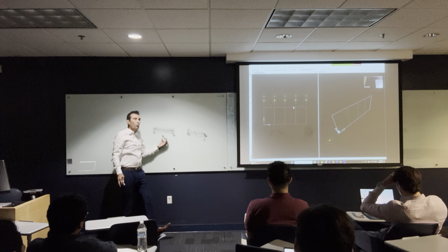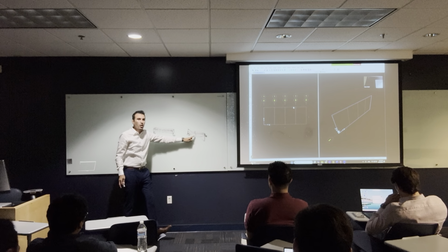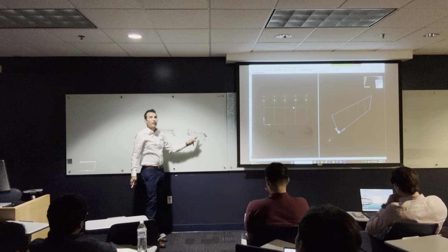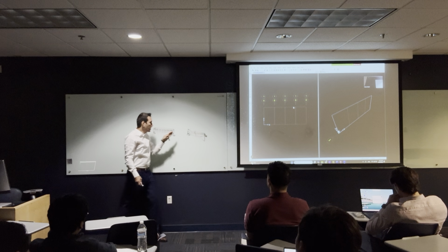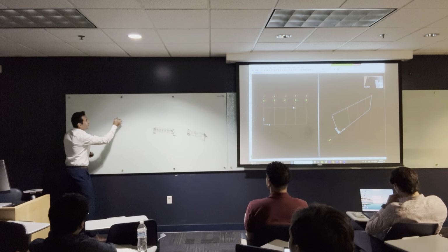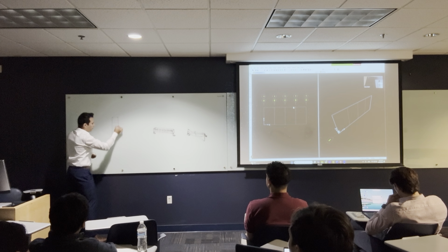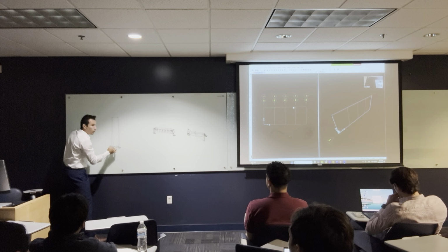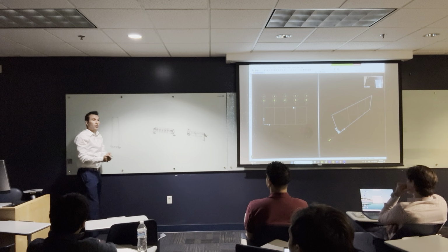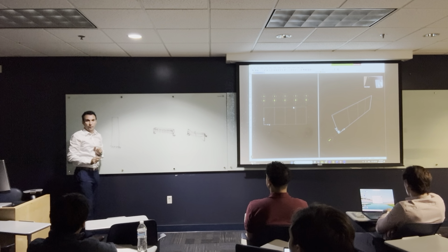Okay, so research-wise, yeah, we can model the beam as a shell. When I was doing my master's, frame was not enough, so I had to use shell to model the beams, and we can discuss it in tall buildings. In tall buildings, we have something called shear walls. Shear walls take a lot of bending moment and increase the resistance of the building.